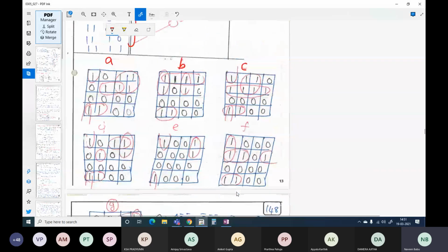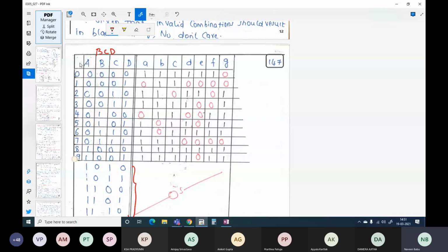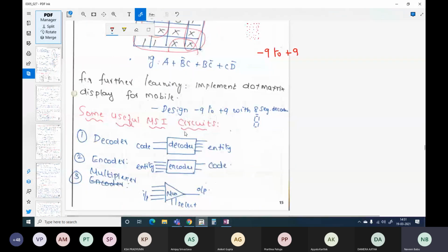So if you want to represent a negative number also, then you will have an additional column for a negative number. And instead of A, B, C, D, E, F, G, you will have A2, B2, C2, D2 likewise for the second 7 segment display. And for the first 7 segment display, only G1 will be there because G1 will be on for all negative numbers. So likewise, you can play around with these digital circuits, right? These are some of the mind-tickling examples that you can think of.